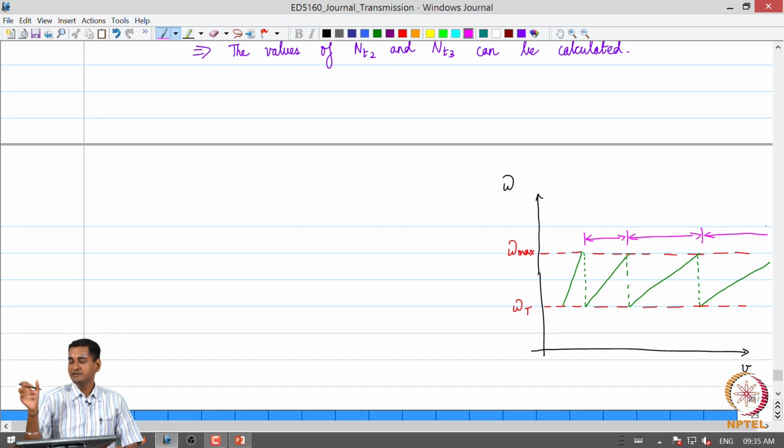So, you can see that the delta V, or the difference in speed between the change in the gears, as we keep on upshifting keeps on extending, with this mechanism of choosing the gear ratios and deciding upon the upshift sequence.